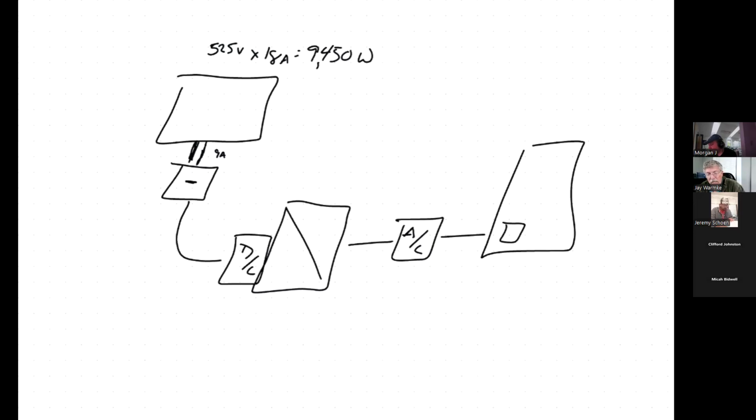If you look at those columns, it's basically saying it depends on which type of wire you're using. Are you using low heat wire like TW or UF wire, underground feeder, for instance? Are you using a medium heat wire? Or are you using a high temperature wire like PV wire or THHN, THHW, those kind of things. Low temperature, 20 amps. High temperature, 30 amps for 12 gauge.